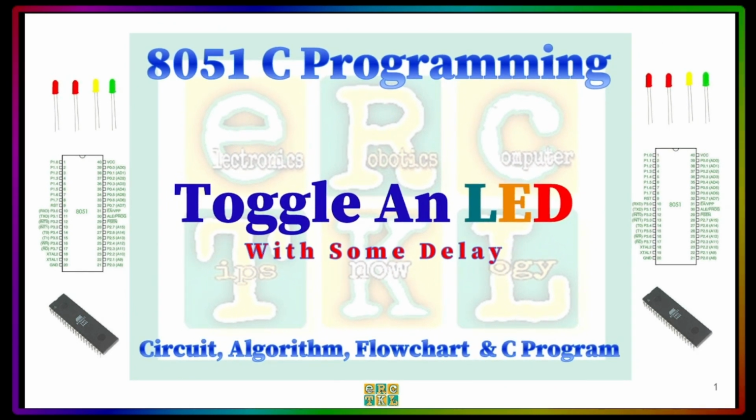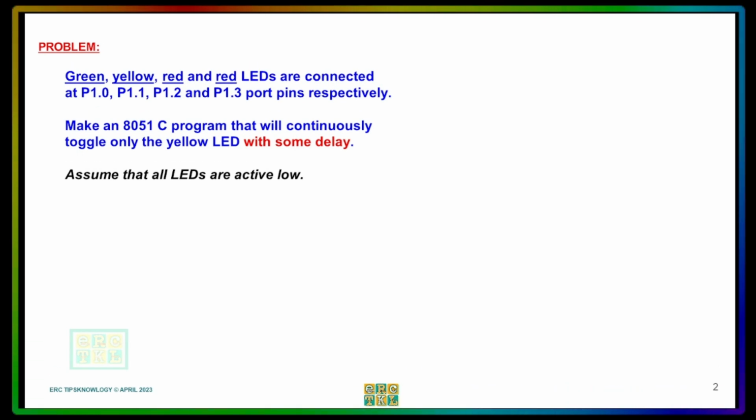The first one is using some delay, and in this example I will be showing you the circuit, the algorithm, the flowchart, and the C program. So the problem is that we have green, yellow, red, and red LEDs connected at port number 1. Port 1 has 8 pins, but we will just be using P1.0, P1.1, P1.2, and P1.3 port pins respectively. So green will be on P1.0, yellow on P1.1, red on P1.2, and the other red on P1.3.